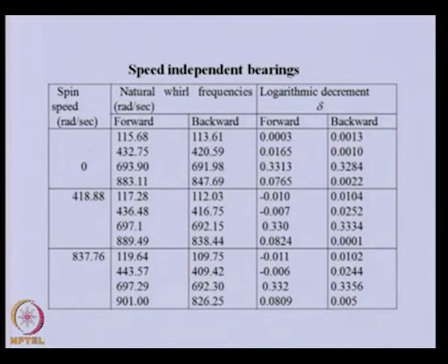So, this is very low speed, basically this is not 0, at very low speed 1 or 10 radians per second, and we found a slight splitting of the natural frequency at this. So, forward and backward whirl, and these are the logarithmic decrement. So, basically in the eigenvalue as we described earlier,